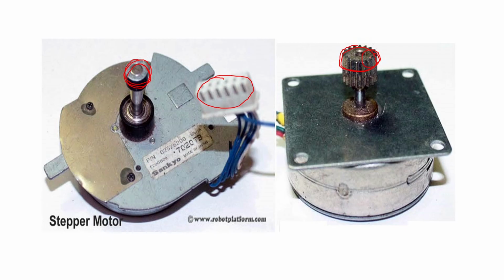features of a stepper motor. A stepper motor moves in accurate equal angular increments known as steps. So it will move in steps in response to the application of digital pulses to an electrical drive circuit. The number and rate of the pulses control the position and speed of the motor shaft. So this is the internal working of this stepper motor.